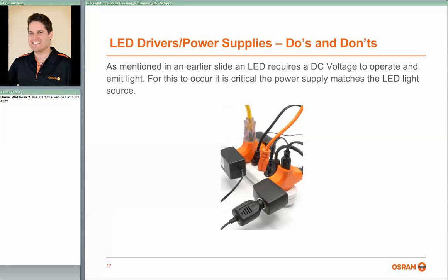Okay, so LED drivers and power supplies, do's and don'ts. As mentioned earlier in the slide, LEDs are a DC light source, so they're direct current driven, meaning that current can only flow one direction. So it's important to make sure that we've got the right power supplies or drivers to go with the product that you want to operate there.